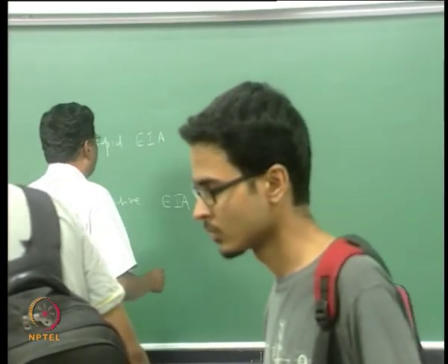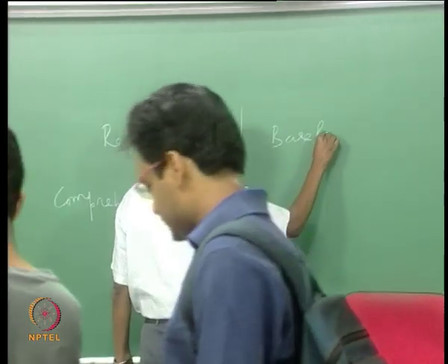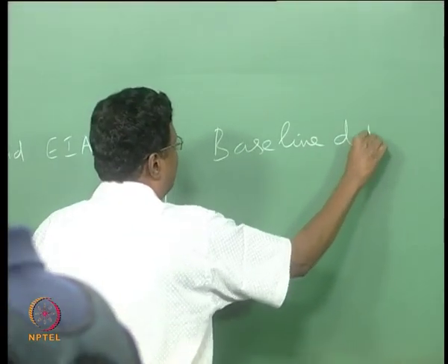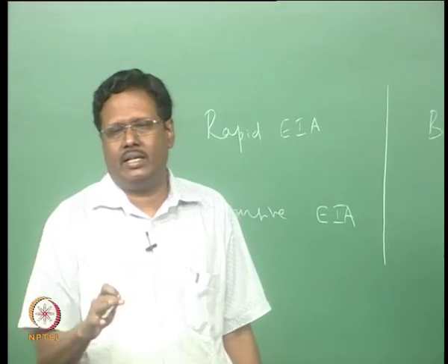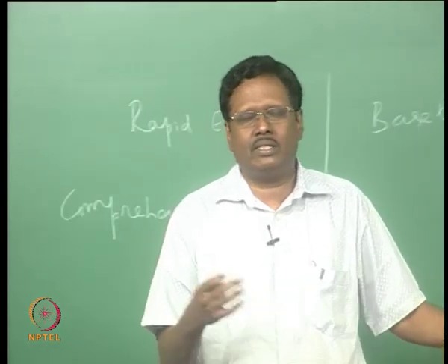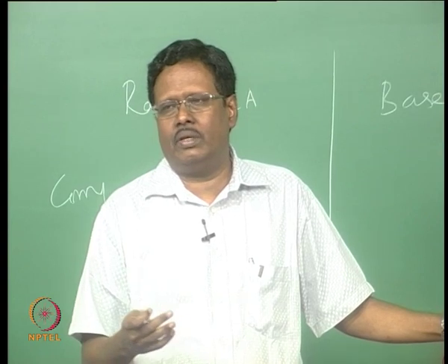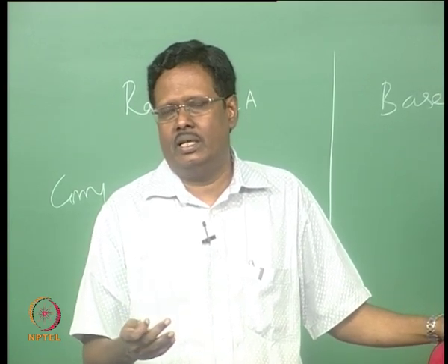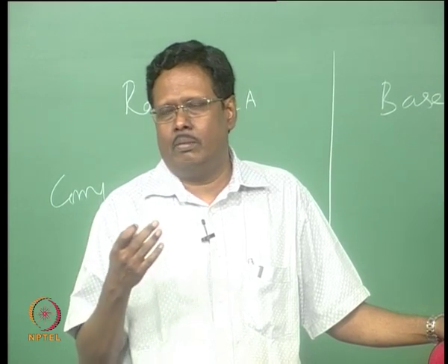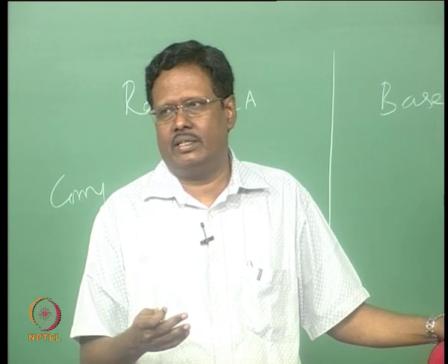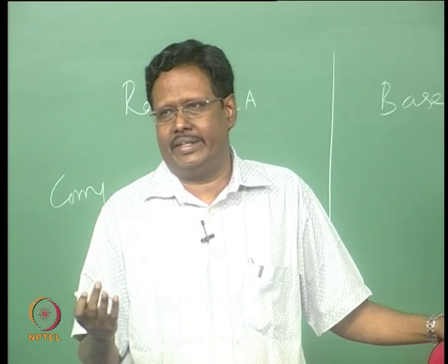So, another important thing what you have to do is, for all this EIA study we need to have what is known as a baseline data. Baseline data means you have to compare with the baseline data what happens later. So, even if the baseline data itself is not acceptable, no point in blaming the developer. Baseline data means before construction of the breakwater or any activity, what are the parameters that have to be first collected. Then you cannot build the breakwater and then measure, that is only monitoring.